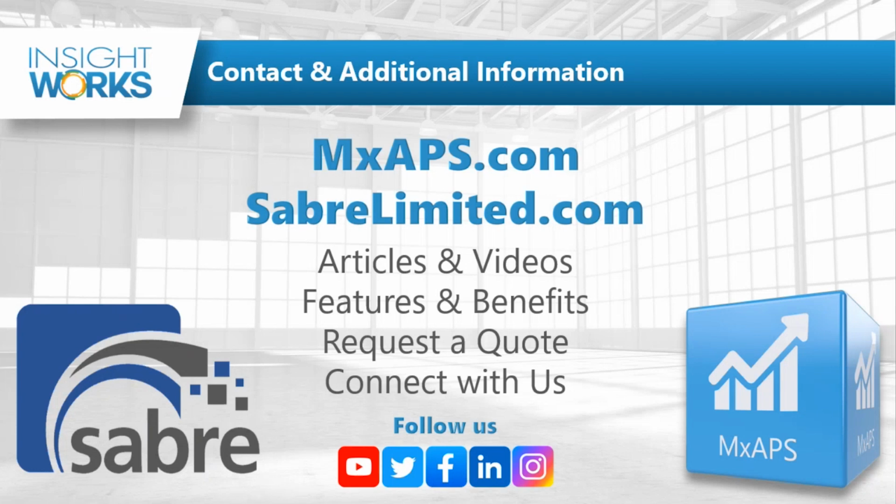And incidentally, we can also do preventative maintenance scheduling through MX as well. And the cool thing about that is you can have a floating PM schedule. So instead of saying, hey, Tuesday morning at 8 a.m., we're shutting this machine down, we can say, hey, within the next few days, we need to do some maintenance. And MX will pick the best time, the least disruptive time to production, to take that machine down to do that maintenance. So we can do maintenance scheduling as well in MX. Anyway, yeah. Hopefully that answered the question.